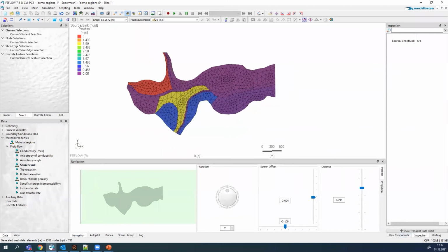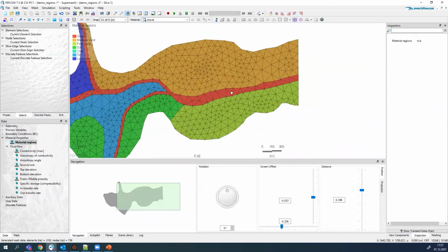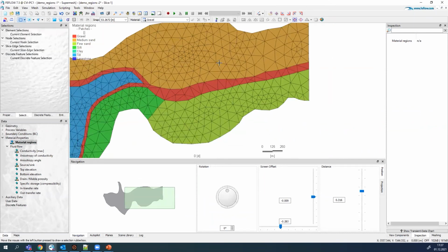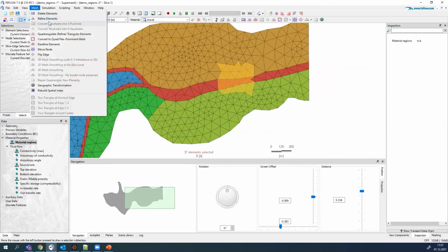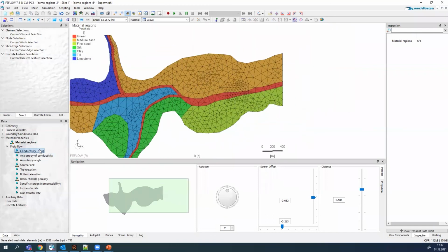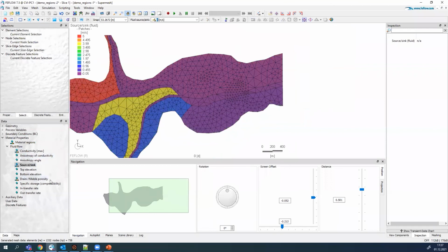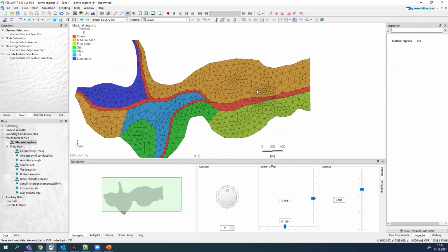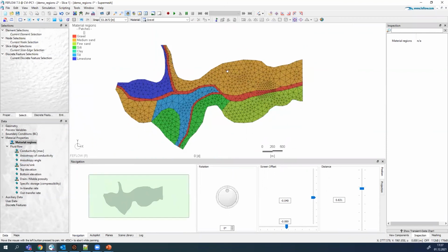All right, so what is also very important to know is that if I look now, let's say I need to modify the mesh. I have to put more elements here because of a specific region. So I can just go and say mesh, refine elements. So FEFLOW will keep obviously bookmarking of the region. So every new element gets the same conductivity. So every mesh operation will update the values as they are connected to the material regions.